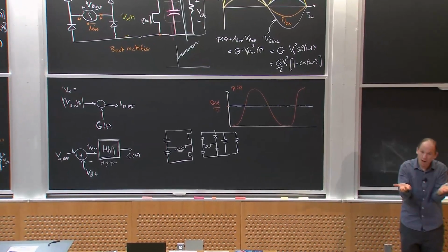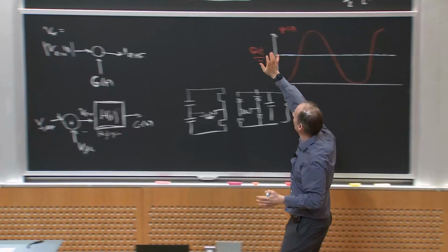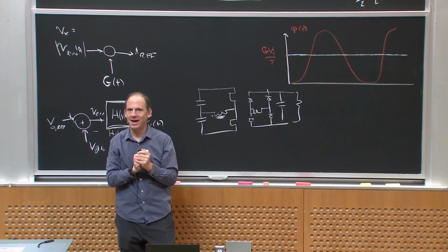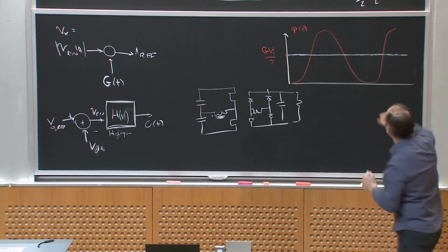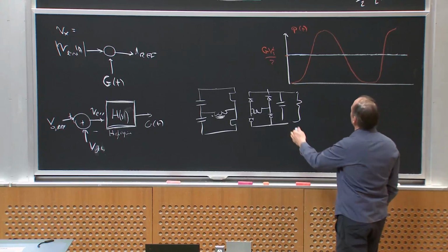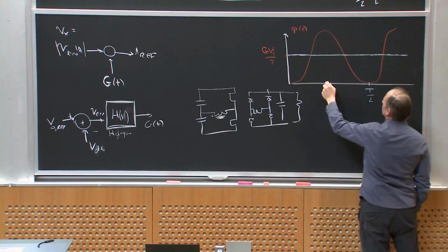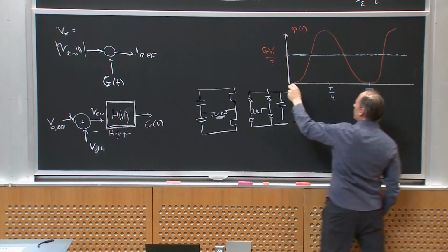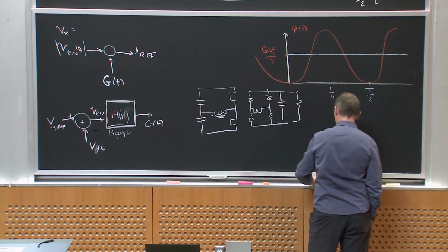Okay? Now the most common place on a PFC converter is to store it across this sort of high voltage DC output, because you can buy very good capacitors there, okay? But what I'm trying to tell you is the energy going into that capacitor, basically, in the first part of the line cycle, I said this is kind of T over 2. This is T over 4, right? In the first part of the line cycle, and if I went negative, it would do this, right?